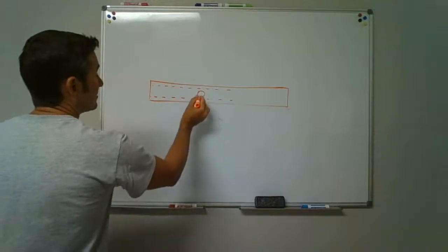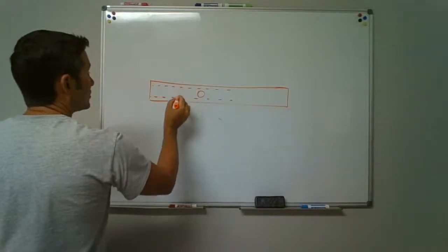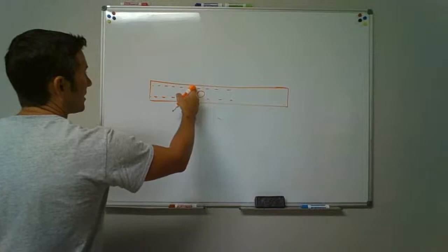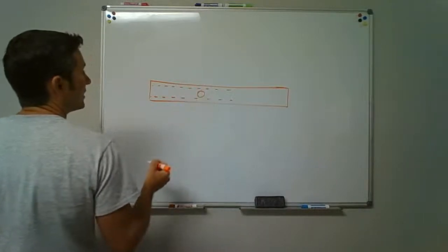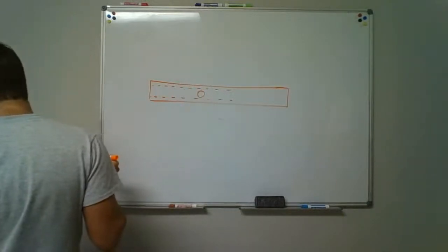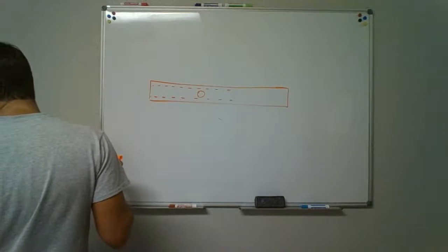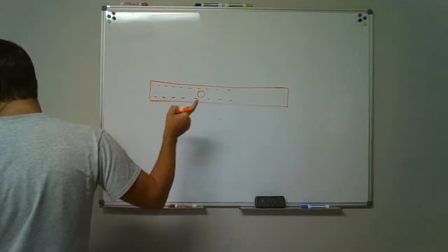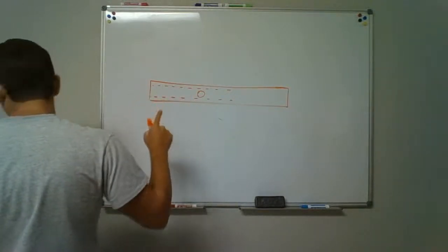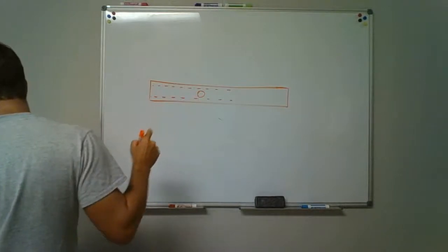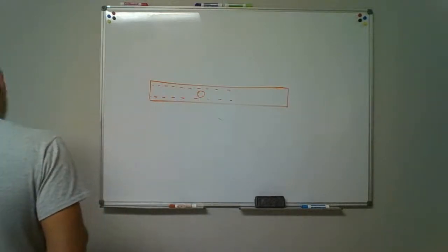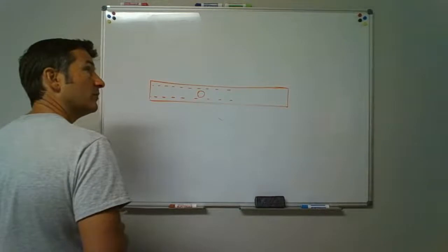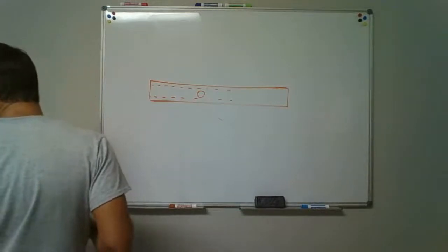Now you can notch out the top of the joist, but it's got to be a notch, okay? And it can't be over the 1/4. Now that was on the ends of the joists for a 1/4. You also have notches in the center portion, which shall not exceed 1/6 of the depth.